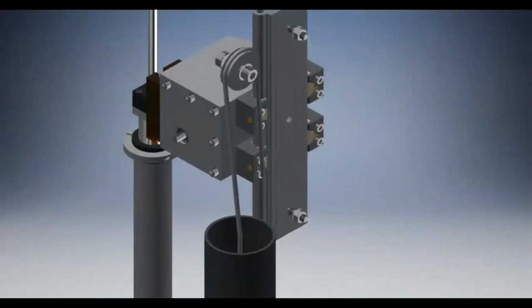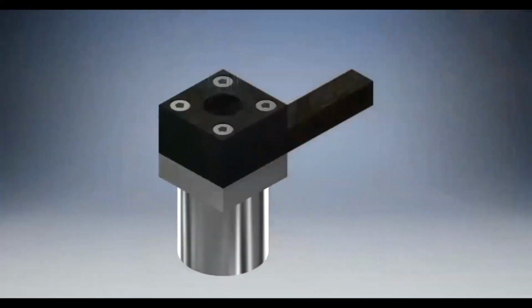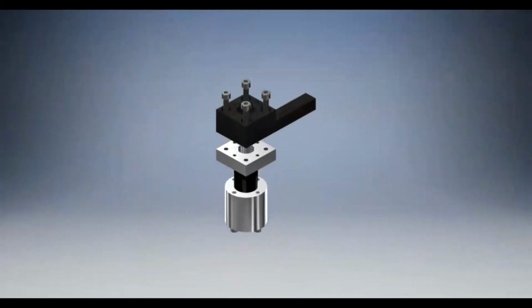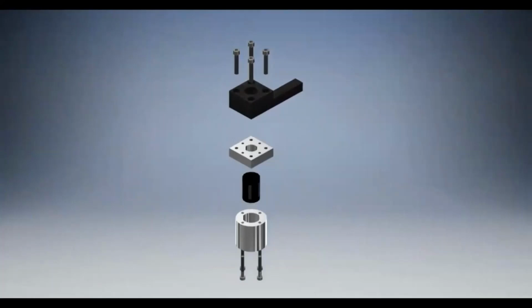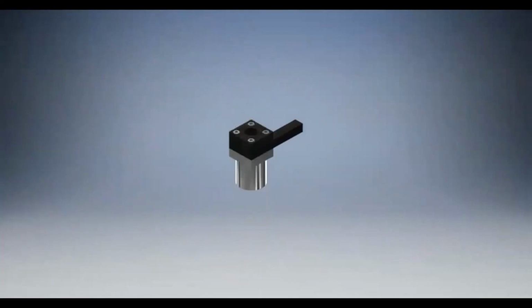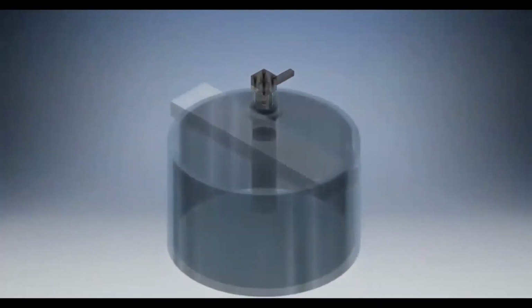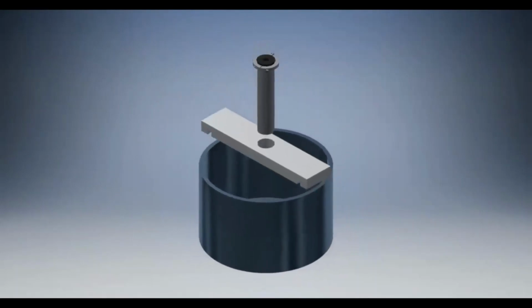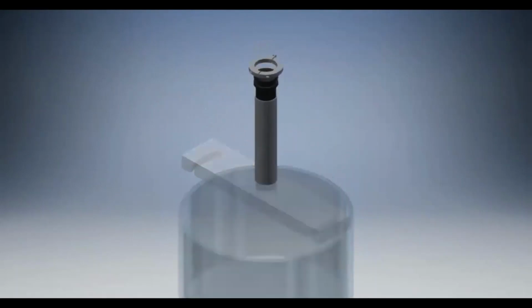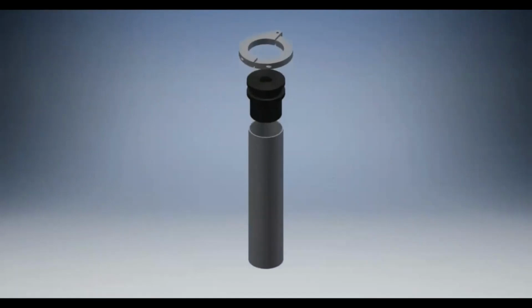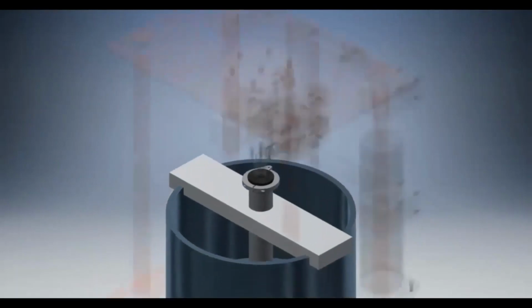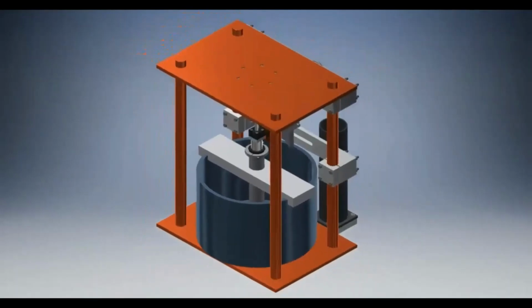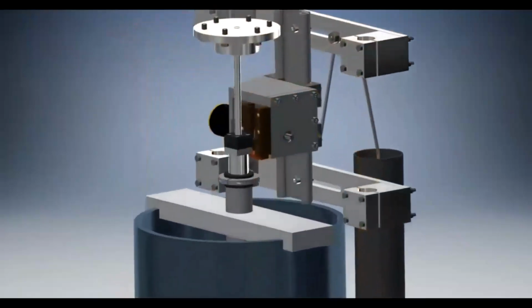And this whole setup will move together when the pile is penetrated to make sure we always have a constant hammering distance. And this is the anvil. And on top of the pile, we also have some special design part which can help us to have a laser system to measure against this and tell us how much we really penetrate the pile in. And this is basically the idea of this whole setup.